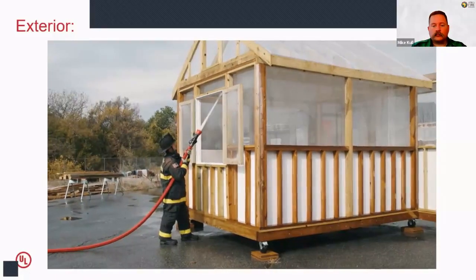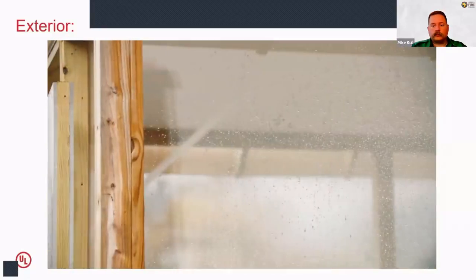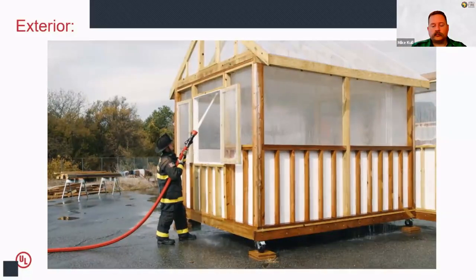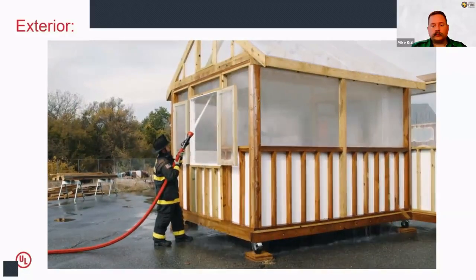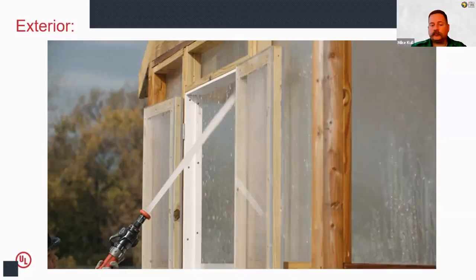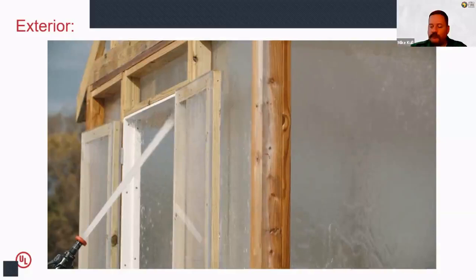The steeper the angle into the compartment, the more water will radiate outwards in all directions, providing better surface coverage and better cooling. As the stream impacts the ceiling and the water radiates outwards, the momentum of the water carries it across the flat ceiling surface common in most residential structures. Once the water has coated the ceiling surface and reaches the side walls of the compartment, it falls down these surfaces in sheets. As the water reaches the floor, it now accumulates in pools in different areas depending on the obstructions that may or may not be present. This water application method nearly simultaneously coats all surfaces within a compartment and is extremely effective in suppression.